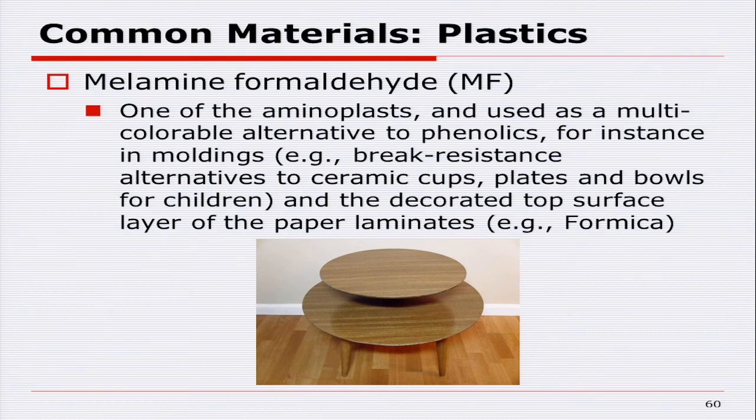Melamine formaldehyde, the biggest use of that is for surfaces on your desk. Yeah, so your desks have that surface on them. You have a melamine formaldehyde surface on the desk that's sitting in front of you. What you have is a paper overlay put on material that's probably a particle board table, with paper over the top and then melamine formaldehyde finish on it.